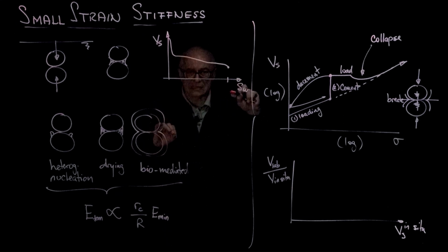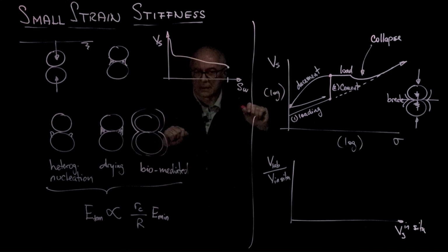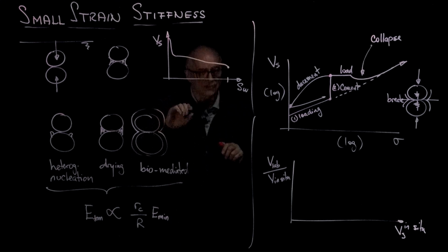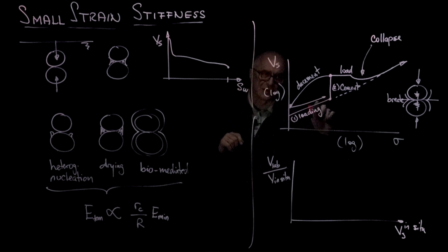The measurement is at the small strain, the process is not. Of great importance to the small strain stiffness is not only the contact type, it's not only the state of stress, but is any degree of diagenesis, which may be significantly impacted during the sample process, not to be recovered during reloading in the laboratory.